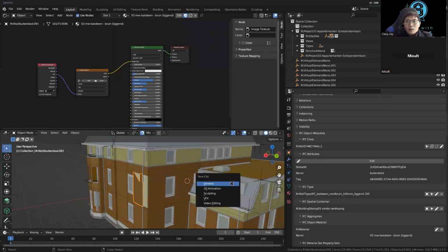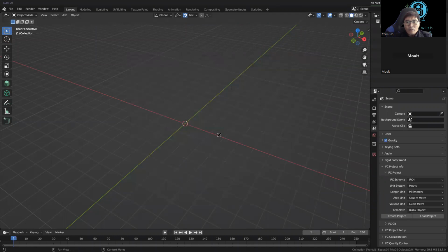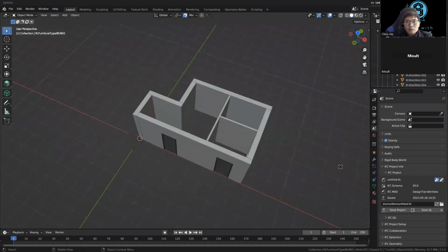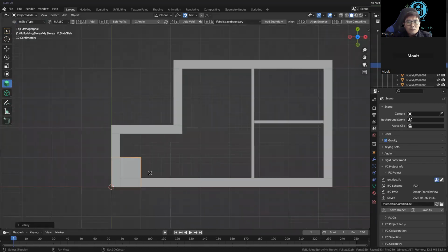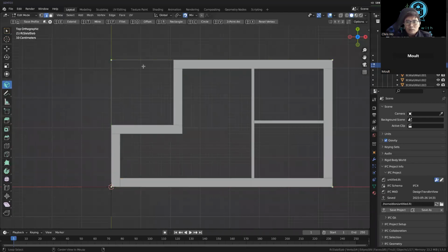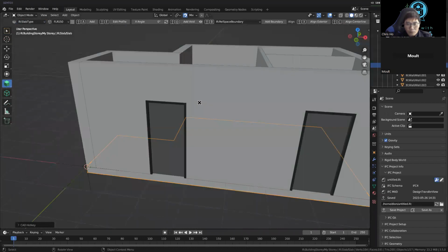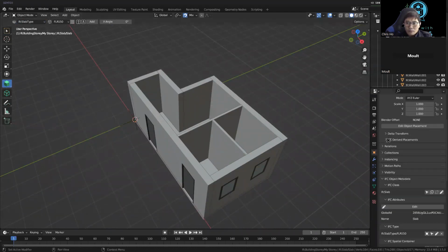Absolutely. So let's go back to our simpler model. And maybe I'll create a slab as well, just so that we have a bit of variation here. So create a slab there, and I'll edit the slab's profile. I'll just snap from there, snap, here, here, and snap that one there. Okay, great. We got a slab. Let's save that.